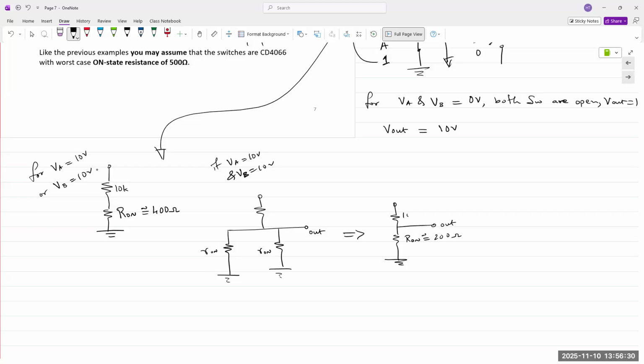Okay. So again, when a single switch is on, you have one single drain, switch resistance. When both switches are on, then you have two of them in parallel. And so effective resistance, REQ, is divided in half. Does that make sense? Any questions?